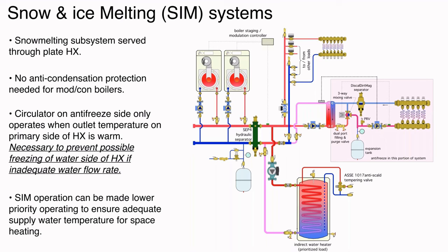Now, I also want to mention the controls for this system would typically make domestic water heating a priority load. And the reason for that is the transient heat transfer rate to a cold slab can be very high. It could basically take all the heat that those boilers are producing and pull the water temperature in the rest of the system well below the temperature where domestic water could be heated. And quite honestly, if this circulator was running, we could actually pull heat right back out of this tank and end up sending it out to our nice cold slab.